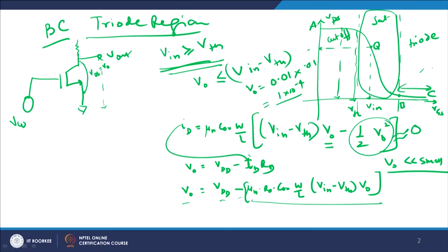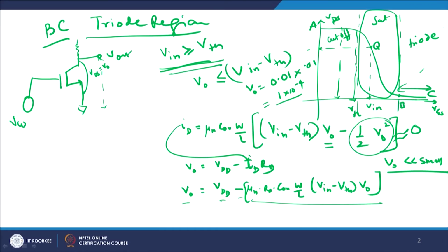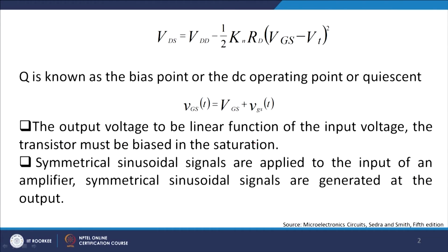You place it in the saturation region, which is this region, and you automatically get a very high gain. This gain is typically very high, of the order of 10, even 10 to the power 2, 10 to the power 3 volt per volt, by doing certain manipulation, of course, and you can do it. Okay, with this let me explain to you what I get from here.